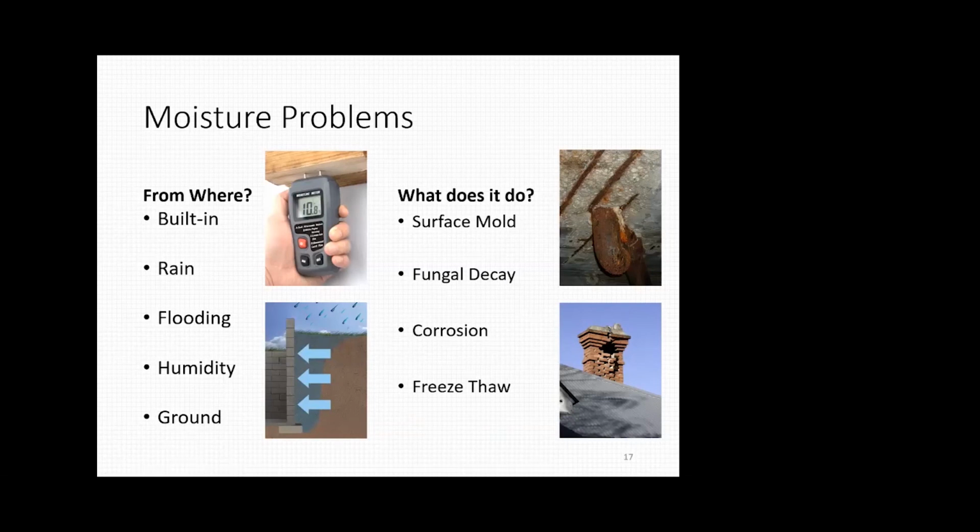So we know that water and humidity cause surface mold, fungal decay, and corrosion. If you get a crack in your reinforced concrete and water gets in, along with the salt and other things, your rebar will start to rust, and it can cause structural failures.